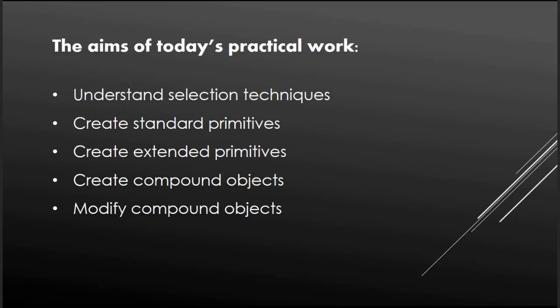In this chapter you'll learn to create the default 3D objects called standard primitives. Thus geometric primitives are parametric objects. You will learn to create complex 3D shapes using extended primitives. Also, we'll learn how to create complex models by combining two or more existing objects into a single object. The different techniques explained in this chapter will help you to combine different 2D and 3D shapes that would otherwise be difficult or impossible to do.